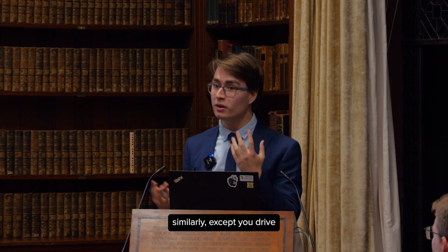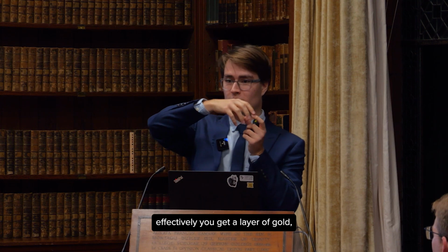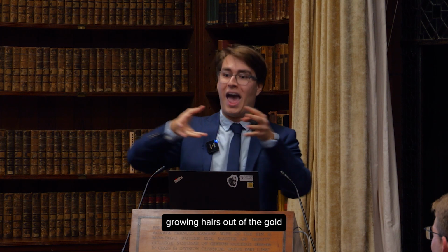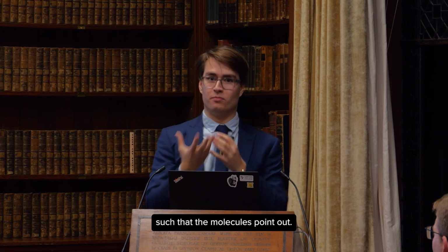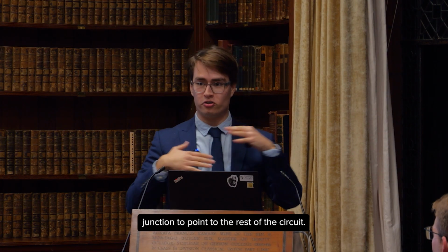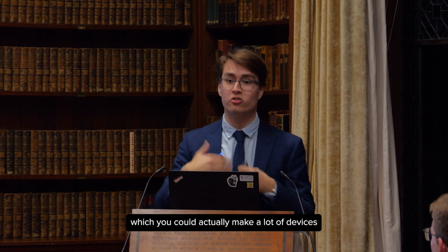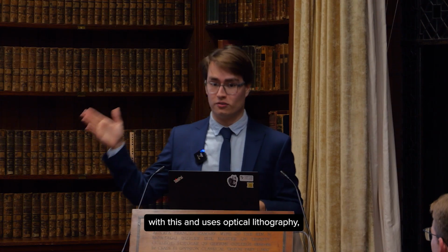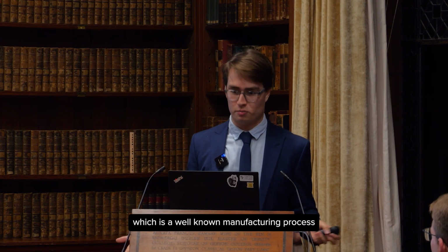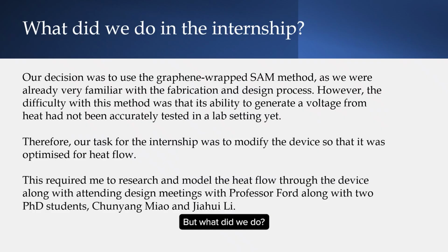Electromigration breaking works similarly, except you drive a large current through, which creates a very small crack. But the one the semiconductor group at Cambridge uses, effectively you get a layer of gold, onto which you create self-assembled monolayers, or SAMs, which is effectively growing hairs out of the gold, such that the molecules point out. And then you can wrap that in graphene, which acts as the other junction to point to the rest of the circuit. This method, compared to the other two, is scalable, so you could actually make a lot of devices with this, and it uses optical lithography, which is a well-known manufacturing process used in semiconductor manufacturing globally. But what do we do?